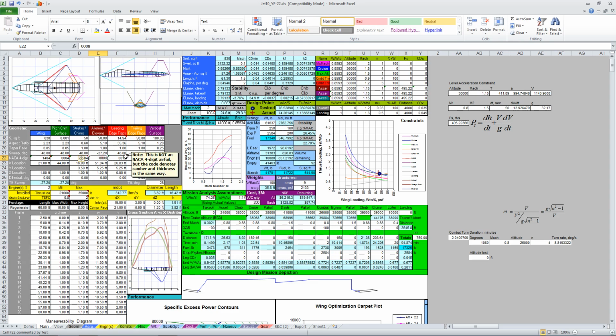This one format for the airfoil section, actually we can't reference that cell. It's a special format, so we just leave it. It's fine the way it is. Alright, so we've got elevons now, and we'll make those things bigger, say 70, and we'll increase the aspect ratio to maybe 8 so that we have nice elevons along the trailing edge of the wing.